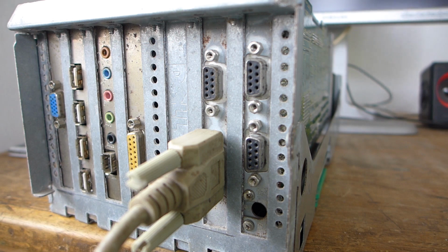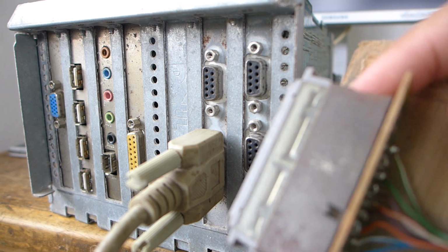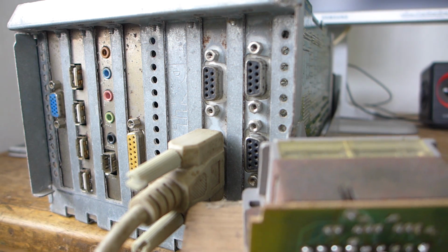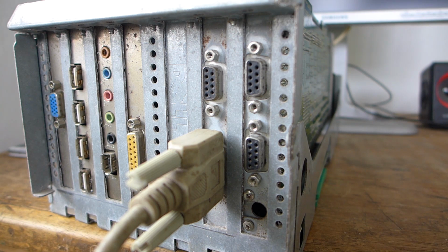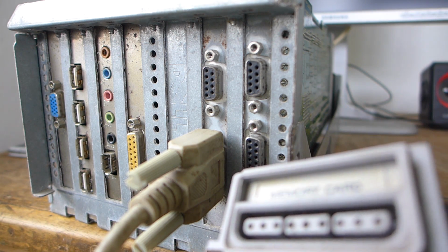As for controllers, I forgot to mention, you can find the pinouts of the multi-AV port of the DTL-H2000 in the PSXDEV guide on how to install the DTL-H2000. As for controllers, I recommend making your own out of parts from the controller connector of a dead PS1, like this one.